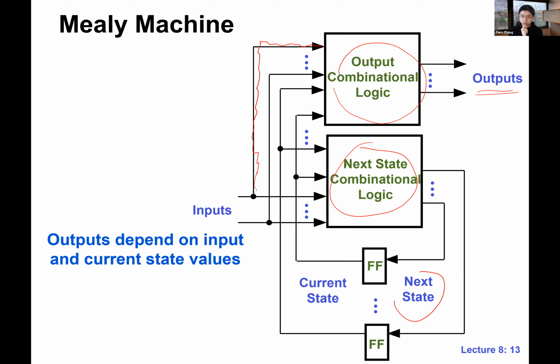So first, one thing that's important is that register in this class always means flip-flop. We do not distinguish between DFF, FF, flip-flop, and register. They're the same thing. But in Verilog, we have something called reg. That reg can turn into a register, wire, or latch. Make sure that you guys are not confused about this.